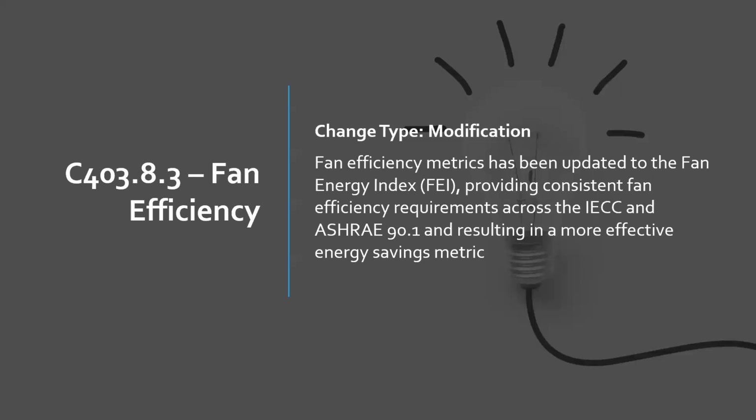And then fan efficacy. This is something new. It's rolling also into residential, but on the commercial side, you've got fan efficacy metrics that are updated with the energy index, just looking at what's the efficiency of these fans. You've got ventilation fans, you've got economizers, you've got warehouse ventilation fans, and they actually need to meet a certain efficiency. So they defined fan arrays, if there's a bunch of them listed in there.